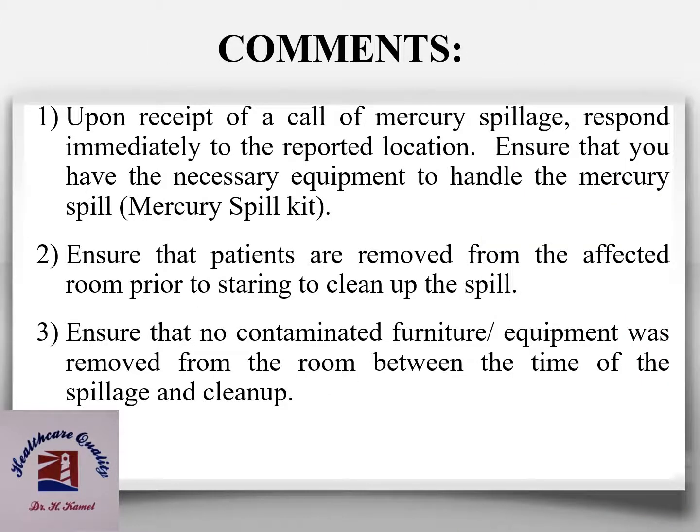Upon receipt of a call of mercury spillage, respond immediately to the reported location. Ensure that you have the necessary mercury spill kit. Ensure that patients are removed from the affected room prior to starting to clean up the spill.